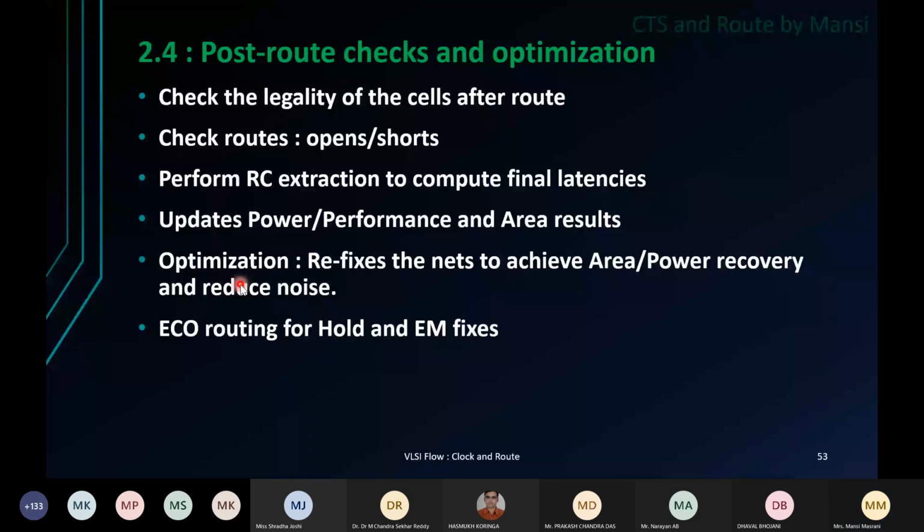In that case it achieves area and power recovery and reduces noise. But one has to make sure that the tool will not be able to recover or refix all the violations. There will be a whole bunch of things left to us to fix. And then finally, it will do the ECO routing for hold fixes and EM fixes. Anybody has questions until now?